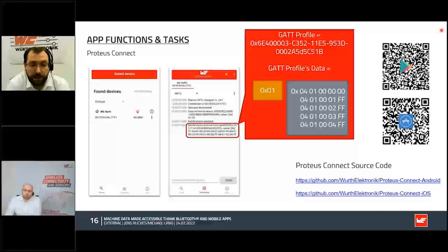In this case, this is an example of receiving the initial status of the LED control directly after connecting to it. In the yellow or orange marking, we see the 1 byte overhead, which is hexadecimal 01, which indicates data, and then some sort of protocol is implemented. And spoiler alert, it looks like it's 5 channels with a PWM value. So that's what's happening here.